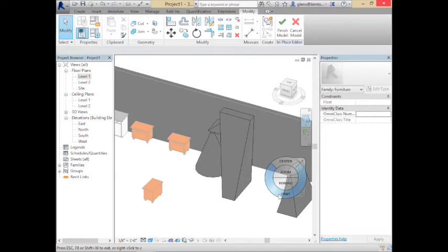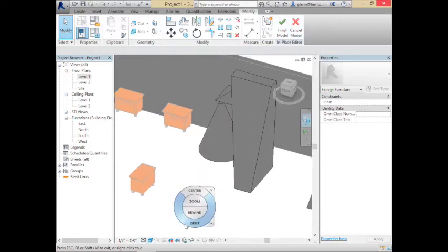We're going to show you the next exciting one that you need to know about, the sweep. And the sweep is actually kind of a fun one. Sweep looks like this. Okay, we've got profiles. We've learned how to take a single profile and stretch it perpendicular. We've learned how to take 2 profiles and get them to morph together. This is all about taking a single profile, but instead of just stretching it perpendicular, we're going to wind it along some path, any arbitrary path you might want to wind it along.